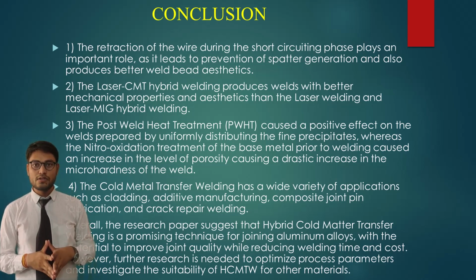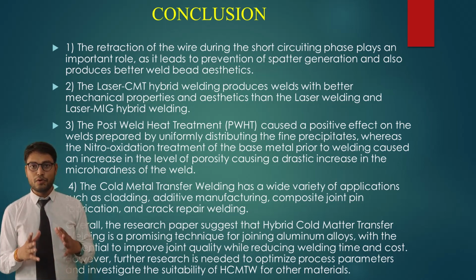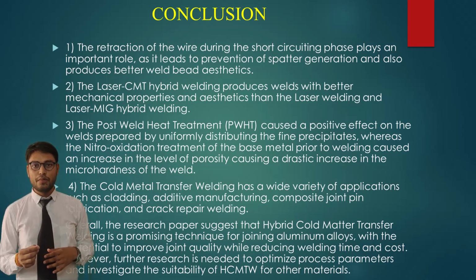The main conclusions of this study are: the first one is that the retraction of the wire during the short circuiting phase plays an important role, as it leads to prevention of spatter generation and also produces better weld bead aesthetics.